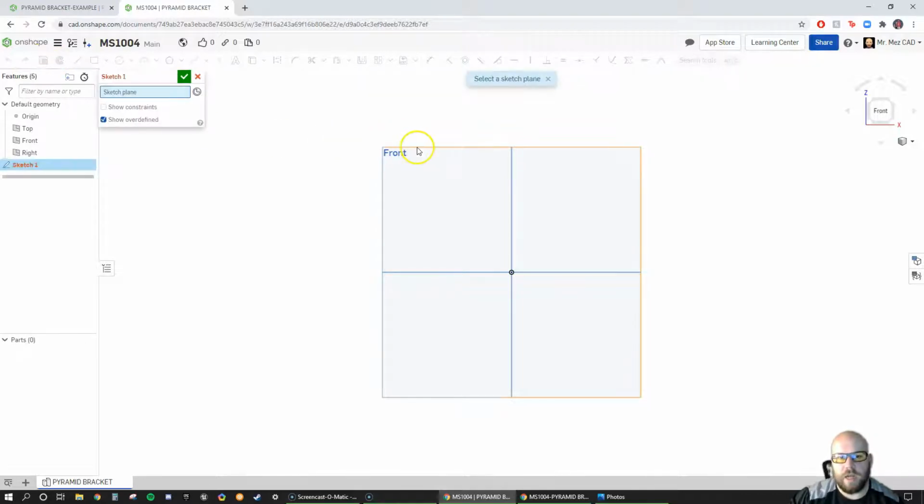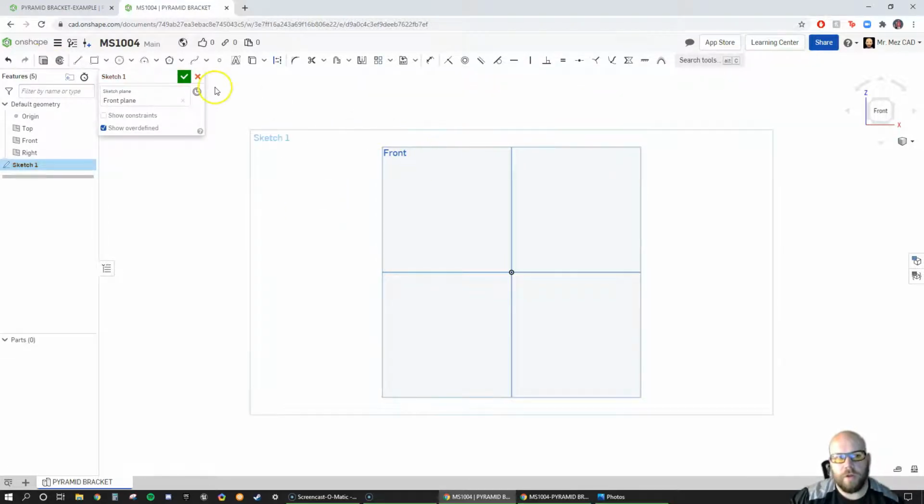and then I'll go back to that sketch. So now I'm going to draw on that front view. I'm already looking directly at it, so I'm going to say I'm ready to go here. So now I'm going to come up to my circle, and I'm going to hover over this one. You can see it may be a little hard to see. There's some dashed orange lines in the background to let me know that I'm in line. I can always add constraints later if I'm off this line, but I like to save time where I can.